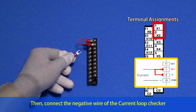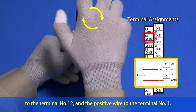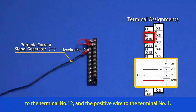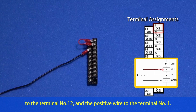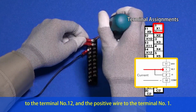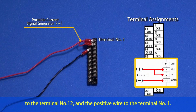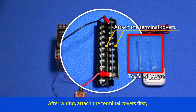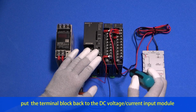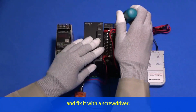Then, connect the negative wire of the current loop checker to the terminal number 12, and the positive wire to the terminal number 1. After wiring, attach the terminal covers first, put the terminal block back to the DC voltage current input module and fix it with a screwdriver.